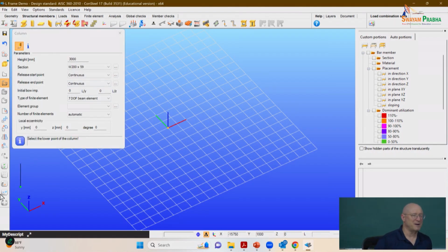Now, we'll be able to illustrate this better with some other cases later. This is a fairly small frame here. Consteel works entirely on, let's draw all the members. Let's get all the members in. We're never explicitly saying, here are the nodes. We're not generating nodes. Consteel handles all the finite element nodes under the hood.